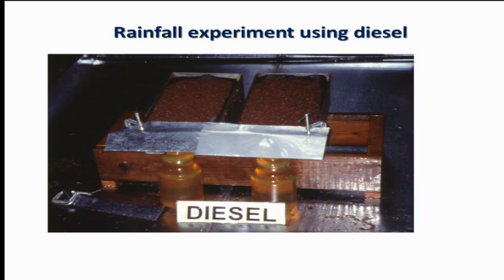It mainly indicated that the charge on the liquid is more important. Water molecules are highly polar with a dielectric constant of about 82, whereas diesel is non-polar, with a dielectric constant of about 1.2. So the charge on the water molecules is responsible for the reaction with the soil. Soils are charged particles, so the charge-charge interaction causes the dispersion problem.